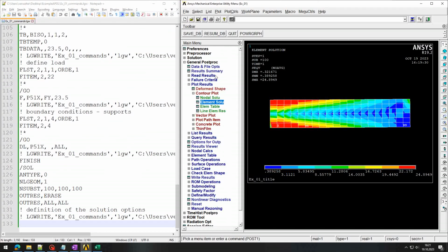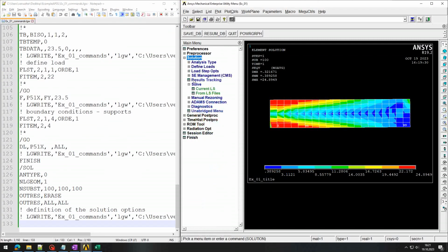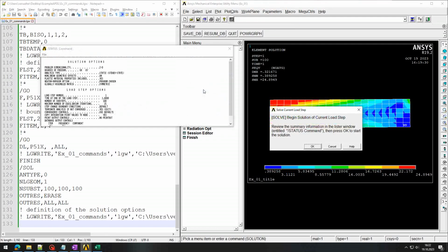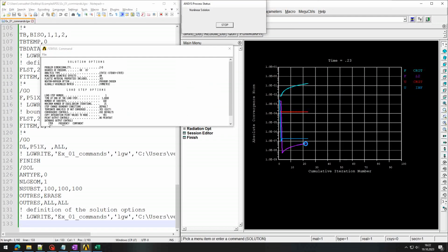We can do that if we go back to the solution and we write the next parameter in the command prompt, defining solution at Gaussian points. The solution extrapolation is set to no, so we will see the solution at the Gaussian point. I click enter, and then we run the model again. We will see how the result changes at this point.